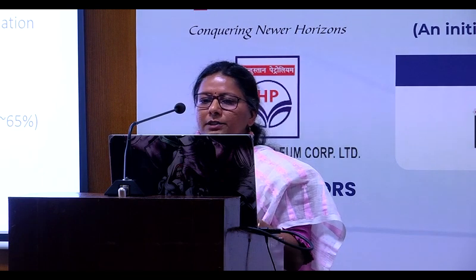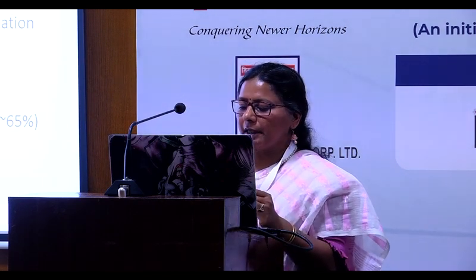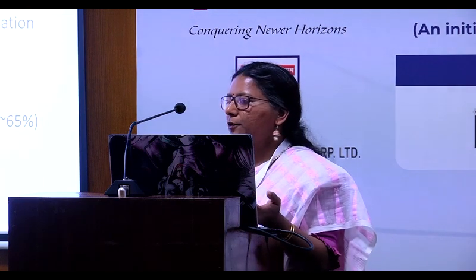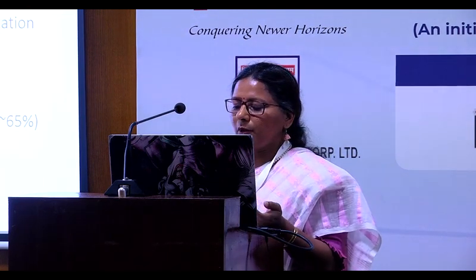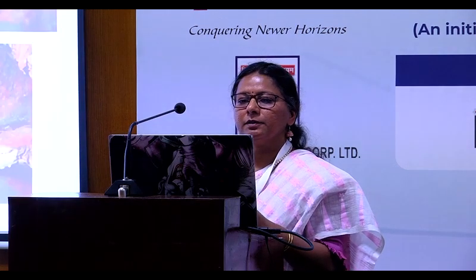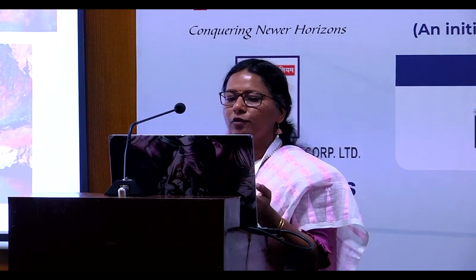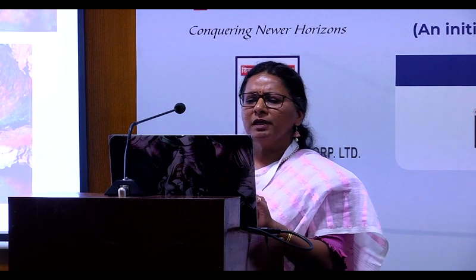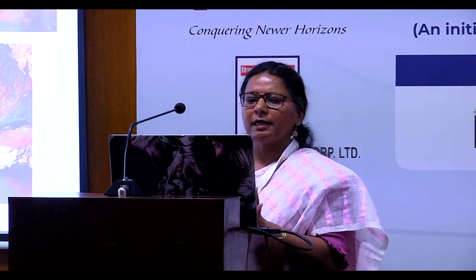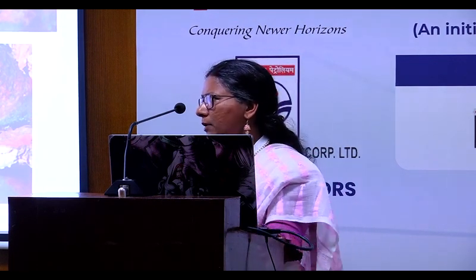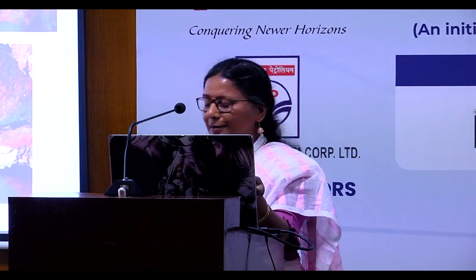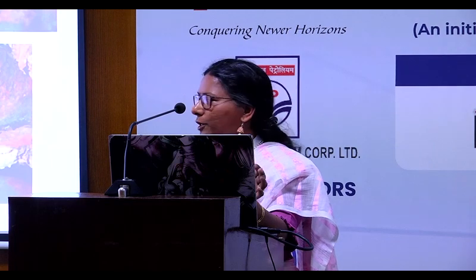Here we can actually visualize, and we need not go with the brute cutting of the insulation for inspection. It is repairable, of course, because it's based on polymers, and it has ease of application. When it comes to inspection, API 510 gives the guidelines where brute forcing is done and it is inspected. For the refinery, we generally identify the line, and then the inspection and coating repair is done locally only. Inspection techniques like radiography or thermography are used.